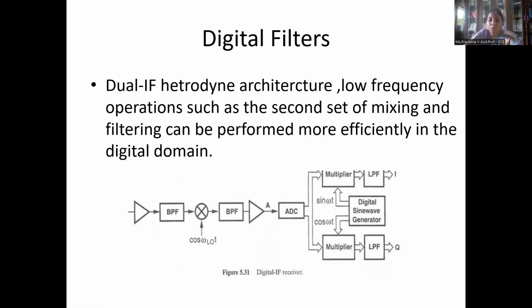where the signal is first processed in analog form and then converted to digital form for final processing. First, the antenna and bandpass filter. The received RF signal from the antenna is very weak and contains unwanted signals. So the bandpass filter selects only the received frequency band.